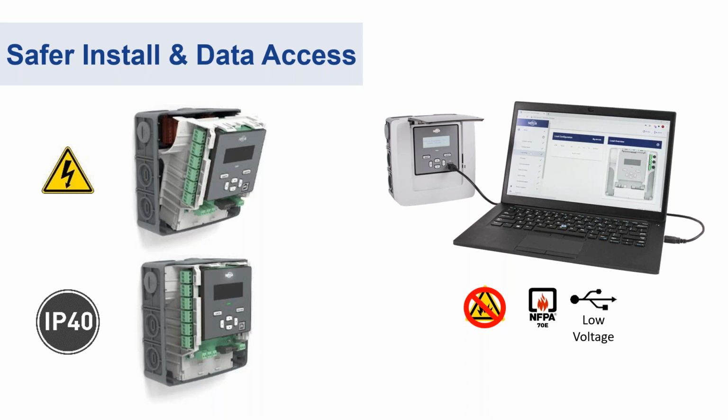As far as firmware goes, the latest firmware is always available on Setra's website, or you can contact your regional sales manager and they'll send it to you, and then you'll be able to update that in the meter itself, either on site or remotely over a network connection.